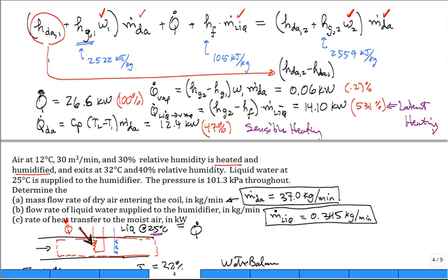I bring air into my building, I heat it up or cool it off, the moisture content changes, sure, but this is how much heat is needed in the cooling coil or heating coil to accomplish this. And if you had not taken into account the amount of heat needed to vaporize the liquid water, you'd have been off by about a factor of 2.